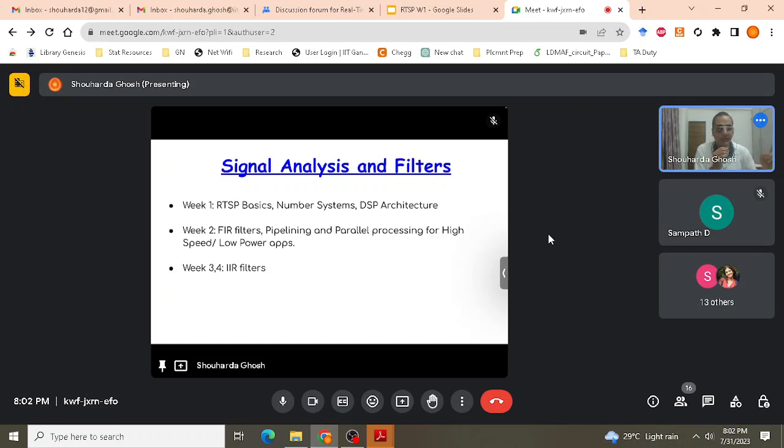You might have learnt about direct form 1, direct form 2, transposition, and other kinds of architectures, some cascade of two structures, cascade of smaller and smaller filters. So what happens over here? The signal processing part ends here, and then some advanced concepts of VLSI as well as a bit of signal processing come into the picture. Some structures may give you lesser noise, some structures may take lesser area, some structures may consume lesser power. So there's a mix and match of everything. We'll be studying that in the FIR filters after briefly reviewing them.